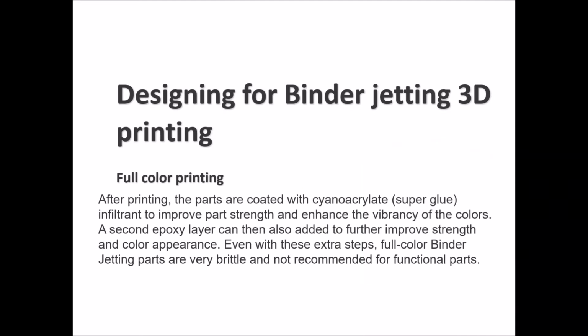After you do your print, the parts will be coated with a super glue infiltrant, so that will improve the strength of the part and it will enhance the aesthetics of the colors applied. Sometimes you add a second epoxy layer so that you improve the strength and the color appearance of your final product even further.